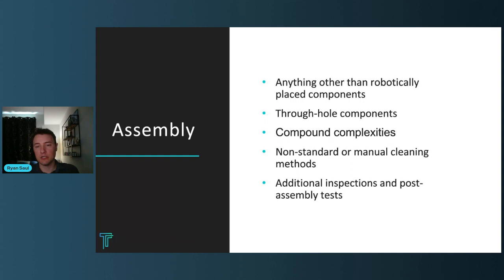Because if you're going through full wave soldering for mass production or selective wave soldering for more of an NPI small scale build, you have to protect that SMT solder joint from the solder wave. And that either is done via a manual process, meaning some technician with a squeezy bottle of mask, or with a hard tool. And in either case, you're adding additional labor or NRE cost to your build.